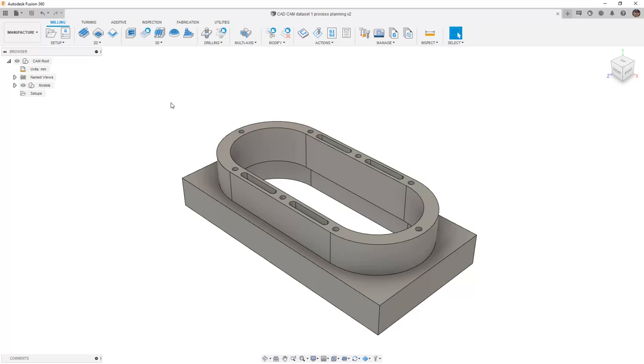Another thing that we want to note when we're talking about using comments in a design is we haven't had to save the design at all. When we expand our comments, you'll notice that it says V2 at the top of the comment. So you'll get a good idea where we placed the comments when we originally created them, which version of the save we were in. Also note that if a design needs to be saved, when we place a comment, it'll automatically save the design for you. So at this point, no save is needed. Let's go ahead and move on to the next step.